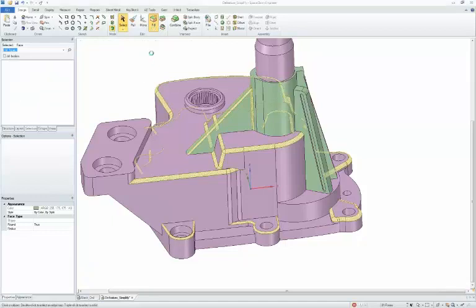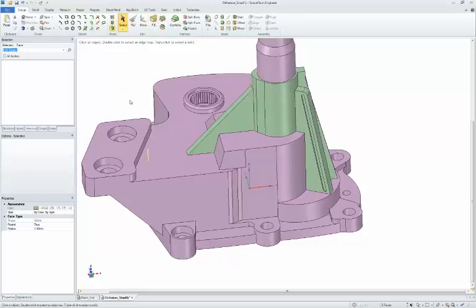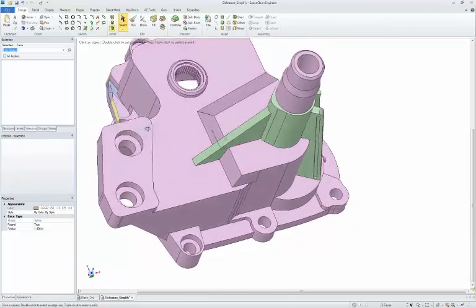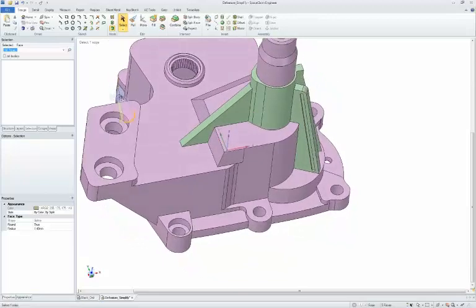And actually, for the shortcuts for these tools, we tried to make them intuitive and simple, so F is the shortcut for fill. So if you see me fill some things in and don't see me click the button, that's what I'm doing behind the scenes. Now you'll notice it didn't remove some of these rounds over here. I'll get to those in a little bit.